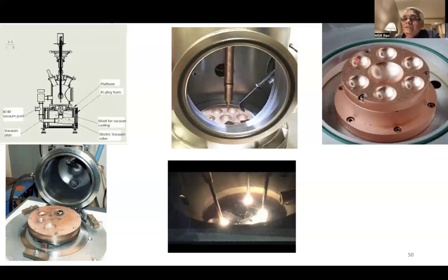Actually, copper should not react, because when you're making a platinum rhodium alloy, if copper is also contributing to that composition, then you're not talking about only platinum rhodium alloy composition. You also have platinum rhodium copper. This is called the copper hearth. The copper hearth is used for multiple uses. The beautiful thing about why copper doesn't melt here is that there is a continuous water circulation around this copper hearth.